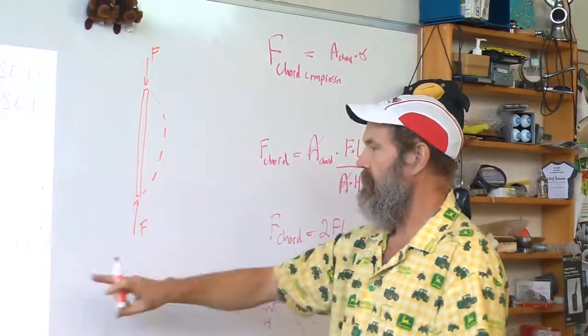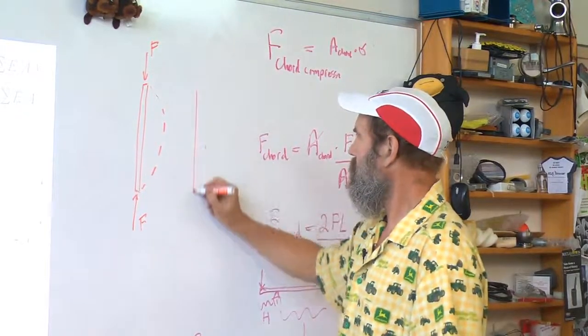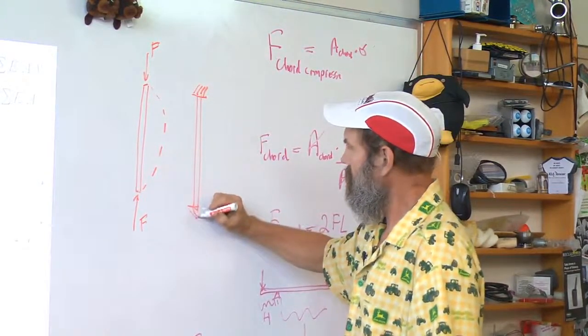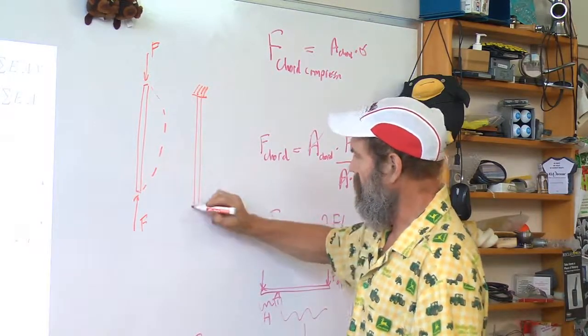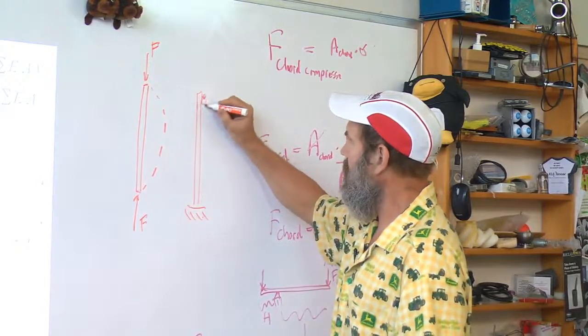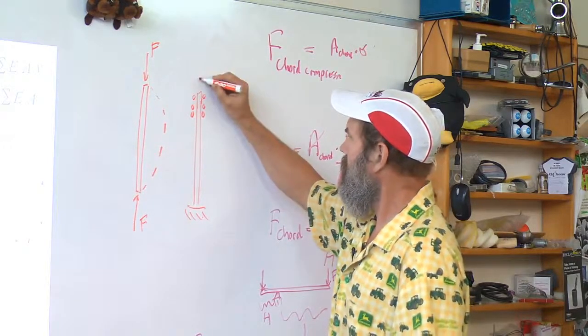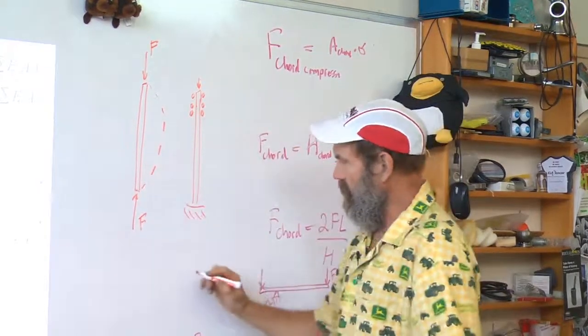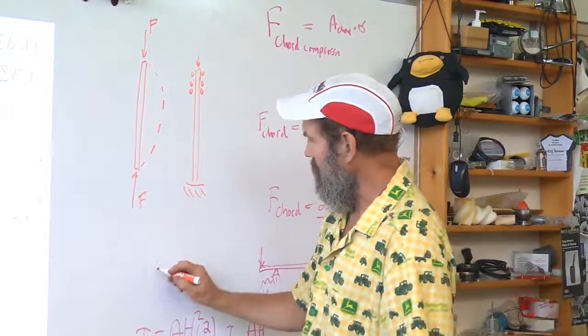And does this column in a truss look like it's built in? In other words, one end would be built in and the other end is guided, so the slope is kept 0 at both ends? Or does it look like it's simply supported?